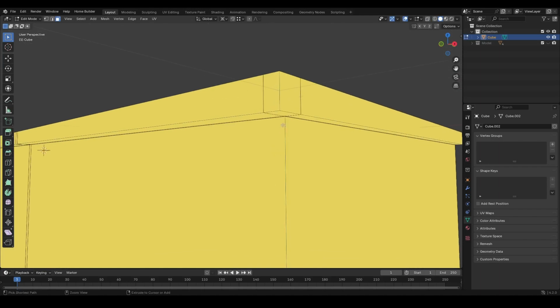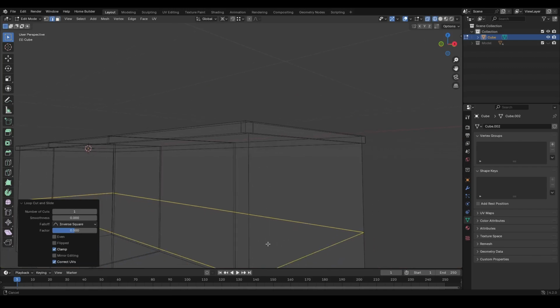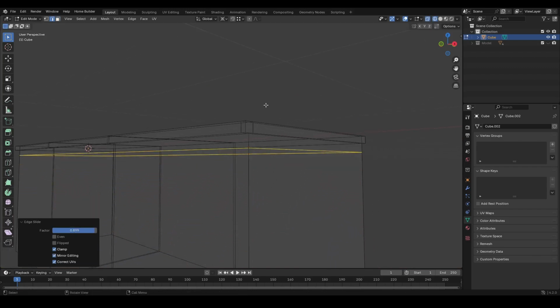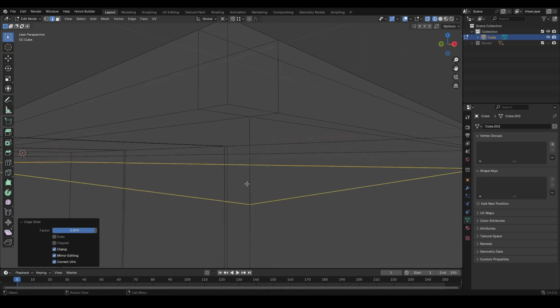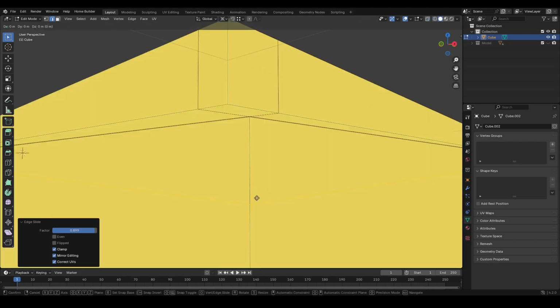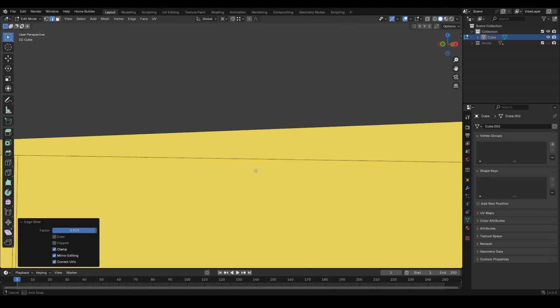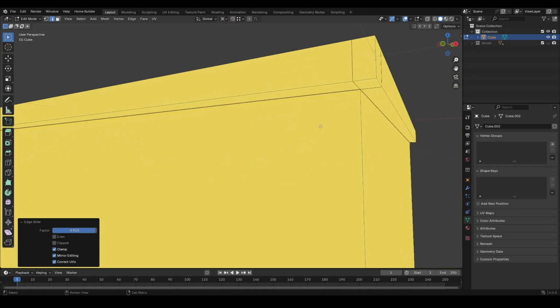In case we want to add some details, such as the original cabinet that you saw, we can assign a new loop cut. So we can press Control R to assign the loop cut, and press G twice to move this loop cut. So now you can see I moved it up somewhere around here because I like to add some interesting things around it.